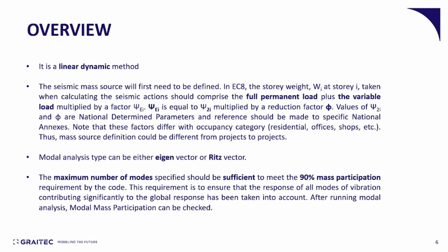You can either allow for only the self-weight of the structure to be excited, or as the Eurocode suggests, allow for the full permanent load plus some amount of the variable load. There are different parameters to define how much of the variable load is going to be added, and each seismic code suggests different values. The modal analysis can give 2 types of results, either eigenvectors or Ritz vectors.